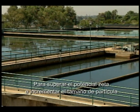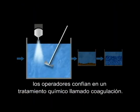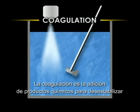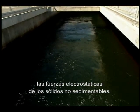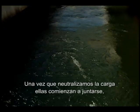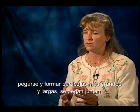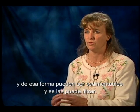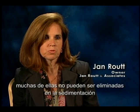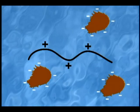To overcome the zeta potential and increase particle size, operators rely on a chemical treatment called coagulation. Coagulation is the addition of chemicals to destabilize the electrostatic forces of non-settlable solids. Once you neutralize the charge, they'll be allowed to come together and stick together and form a larger and larger particle that can either settle out or be filtered out. If you didn't treat them chemically, most of them just would not come out. They'd go right through your filters and go right on.